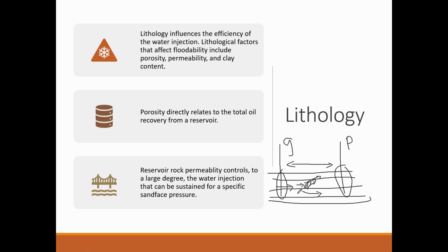So basically, permeability can be measured on a well scale, but the interwell connectivity is very much important, which is not known to us, and this is totally a stochastic measurement. And what is happening inside the reservoir is least known if we are trying to just inject in a particular formation and we are not seeing it in the producer. So the interconnected permeability is very much important from the point of view of injectivity.